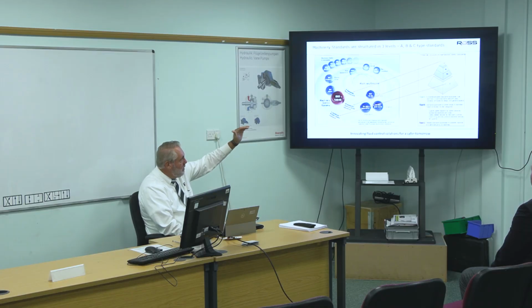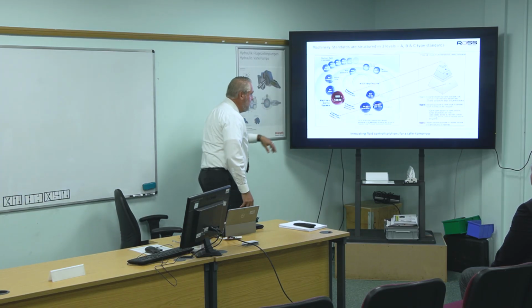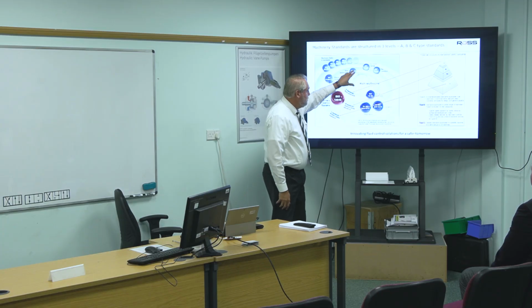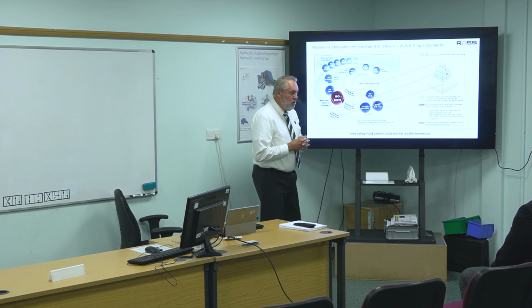And the way the standards are structured is in what they call A, B, and C type standards. Your A standards are what they call general safety standards or basic standards, and that deals with risk assessment and basic risk reduction. You get into the B type standards. These are more generic for technologies.